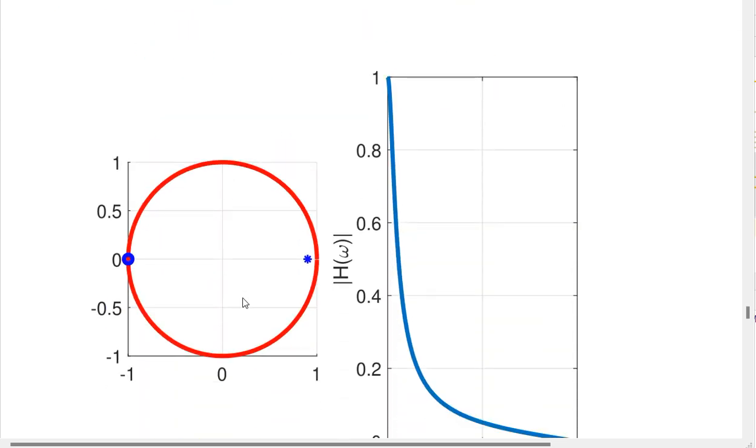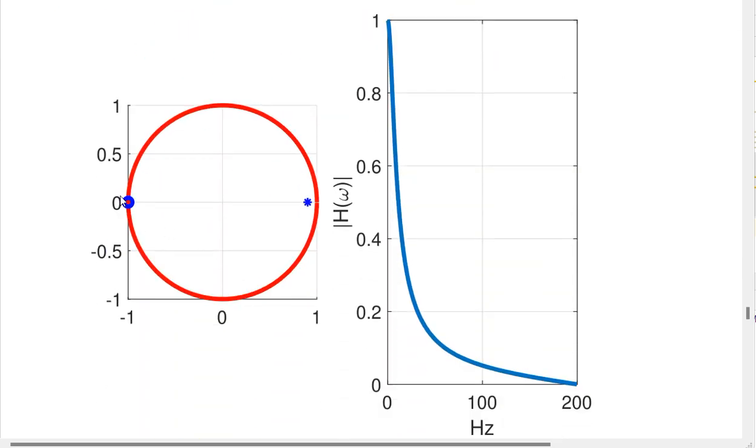Okay? Now, it shows the idea. Just have a deep look here. Zero appearing in 180 degree because it's going to remove the higher frequency because it's low pass filter. So higher frequency should not have permission to pass. Meanwhile, amplifying the low pass frequency. So amplifying will be done by poles and preventing the pass will be done by zeros of the system.